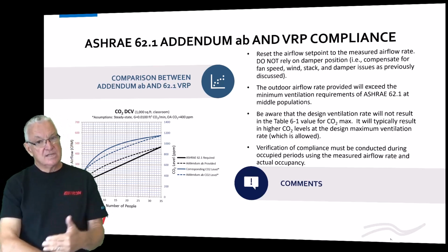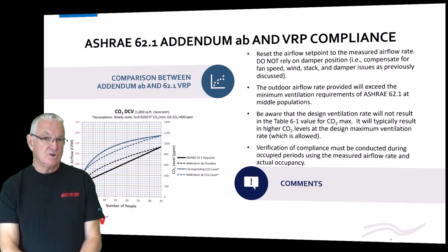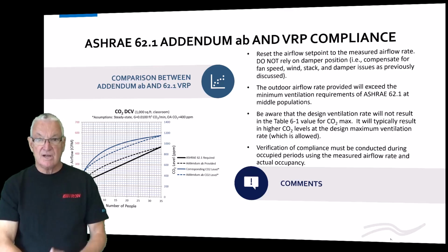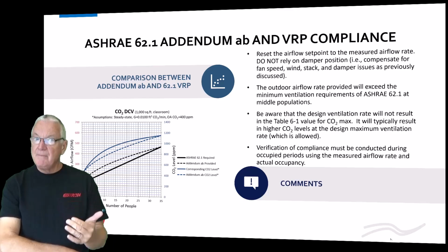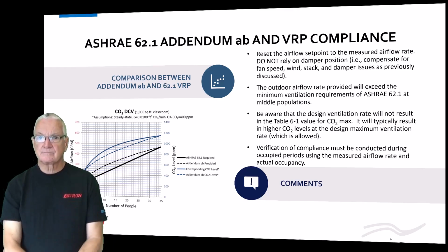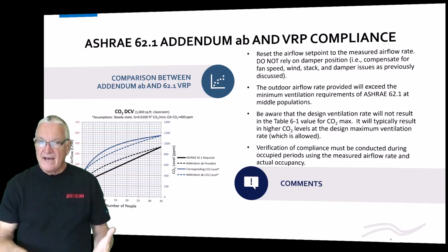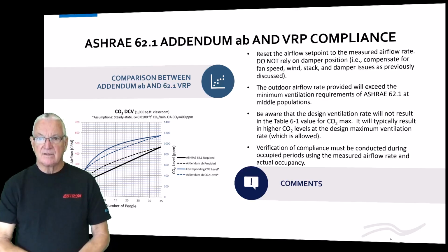But also notice the CO2 level varies. It's not a fixed CO2 level. So I have some comments here. Yeah, accomplish this by resetting the outside airflow set point based on the CO2 level. I like that.